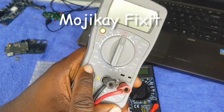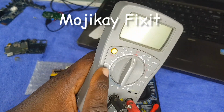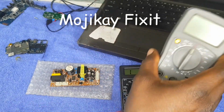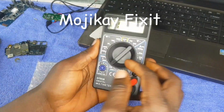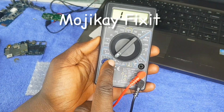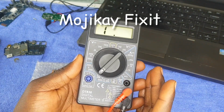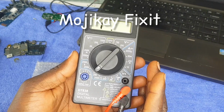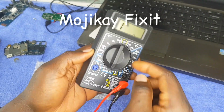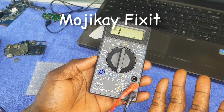So you can see on this multimeter is written ohms. So right there, that is where you take your resistance reading or resistor reading. Okay, now putting our multimeter on this, it's better to put your multimeter on the higher side so that you can get the accurate reading of the resistor. Or if you are very sure of the resistance of the resistor you are reading, then you can put this dialer wherever you want to put it.